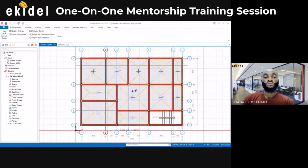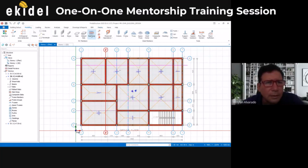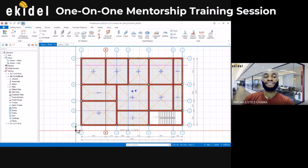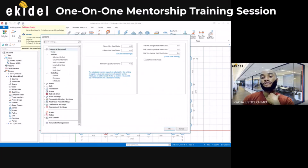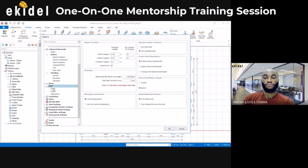You have to go to the modeling tab here, then you see slab strip. Before the slab strip, you can come to your slab settings and set your maximum spacing that you want. Come to slab here, then come to this place.